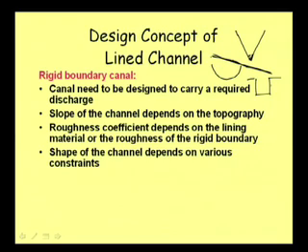And as I was already telling, for a rectangular channel, suppose this sort of cutting is there, and if this is sandy soil, it will not stand, this will fail, and if it comes here, this sediment will block the flow and create problems. If we give lining, the chance of failure is less, but the cost of lining required to prevent the failure may be much higher.